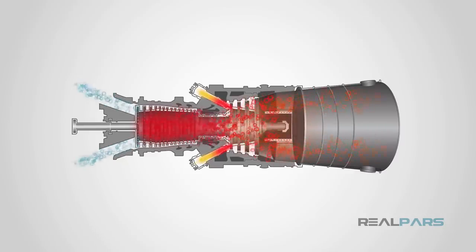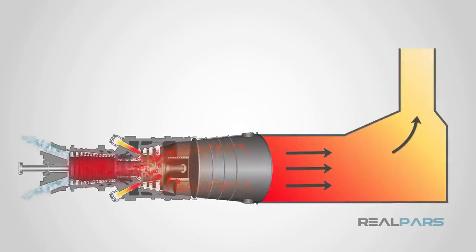When the fire is established and stabilized in the combustion chamber, the ignition system will be put out of service. The most critical process in normal turbine operation is to manage the combustion and produce a proper amount of high-pressure exhaust gas. This exhaust gas is applied to the turbine blades, and after rotating the turbine shaft, conducted to the exhaust stack.